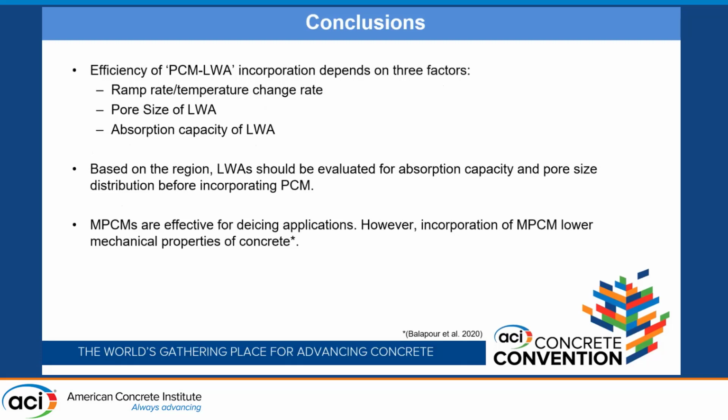Based on the region, lightweight aggregates should be evaluated for the absorption capacity and the pore size distribution before incorporating the PCM in them. And also, microencapsulated PCM are actually effective for de-icing applications. However, this study has already been done in our lab. Microencapsulated PCM actually lowers the mechanical properties of the concrete, which is up for further discussion as future work.